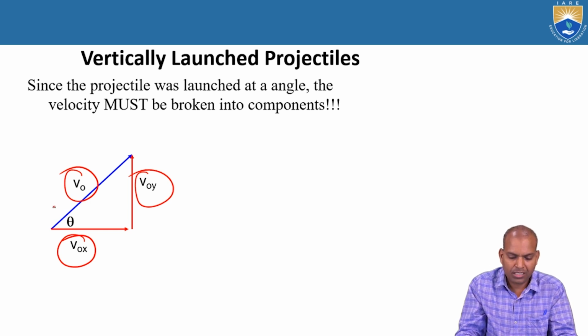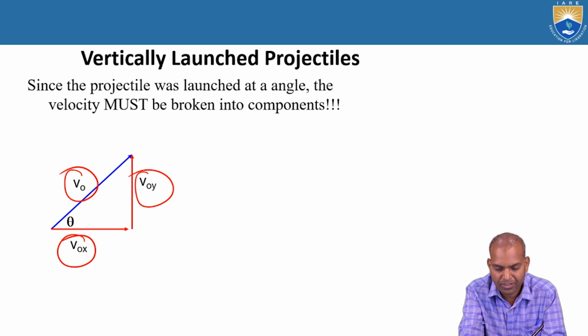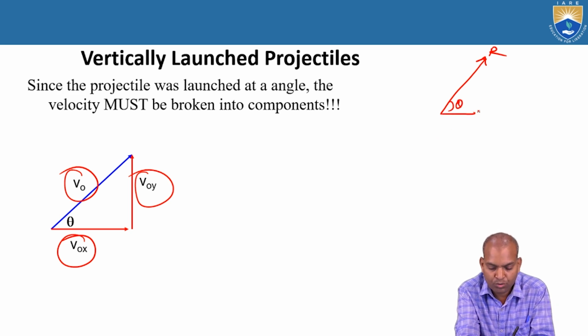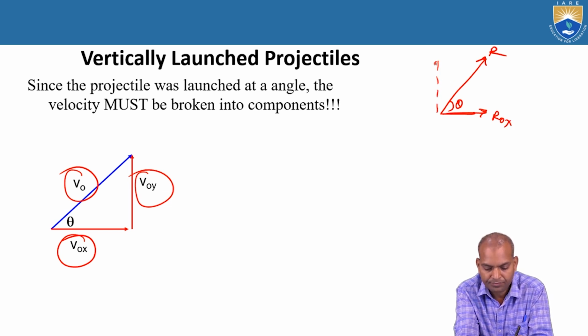This is the same concept we discussed previously in the fundamentals of engineering mechanics. There is a resultant force with some angle, and we have to resolve it into two components, Rx and Ry. Rx equals R cos theta, whereas Ry equals R sin theta.